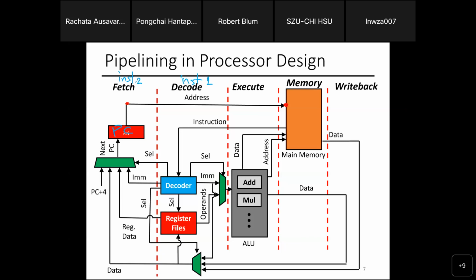You got my problem here. I have multiple instructions in my pipeline. Some place has instruction 1, some place has instruction 2, some place has instruction 3. And many of these components are combinational logic. It's designed to handle only one instruction in the whole design. So the solution has to be this. I need to have an intermediate thing to store instruction 1's data. Then I have to have intermediate things to store instruction 2's data. All right. Otherwise, I lose progress.